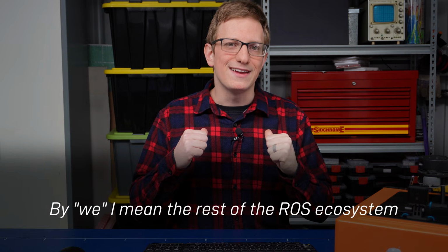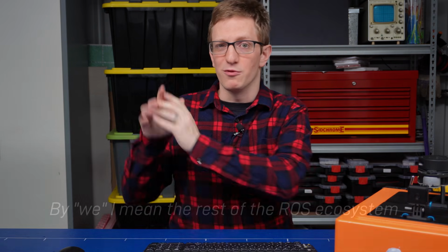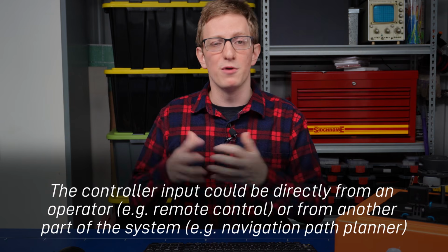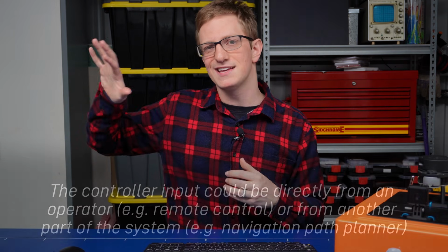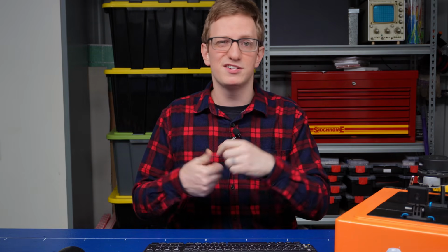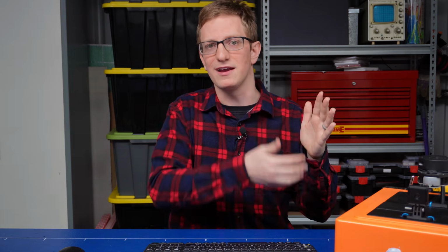So that's the hardware interfaces, but what about the controllers? Controllers are the way that we interact with ROS2 control. So on the one end, they're going to be listening for an input on a ROS topic. That could be something like joint positions in a robot arm or mobile robot body velocities. They're going to take this input, calculate what the appropriate motor positions and speeds and that sort of thing are, and then send these to the hardware interfaces that have been exposed by the resource manager. While the hardware interfaces need to be designed specifically for individual hardware, the controllers are going to be designed specifically for different robot applications.